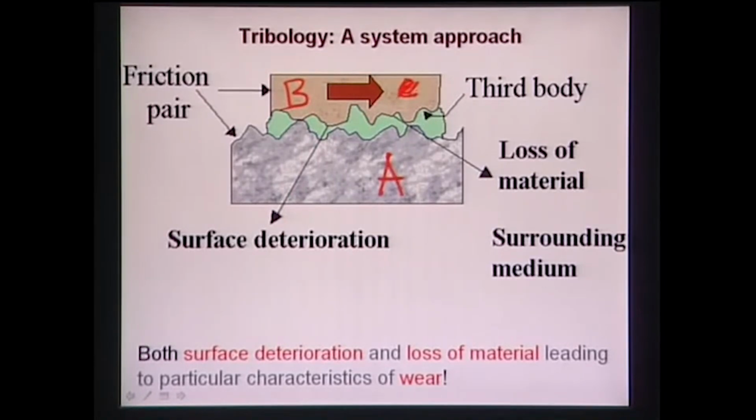The other thing that I am trying to mention here is that although both A and B, if you look at them with your naked eyes, you will find that they are perfectly smooth surfaces, but microscopically they are not smooth. They always contain this kind of hills and valleys, which is scientifically known as asperity.